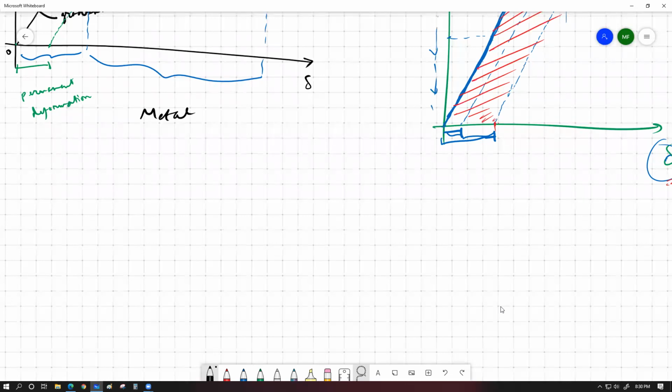This behavior is equally applicable for molten glass as well. If you melt glass by applying enough heat and then pull it apart, you can actually make strings out of glass. So materials can behave differently depending on temperature. Temperature is a very, very important factor. For example, the reason iron and other metals are heated up before they are shaped is that whenever they are hot, they undergo permanent deformation more easily.